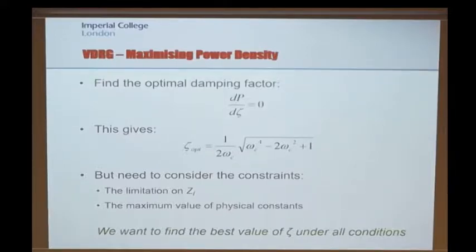Your spring won't be able to tolerate the amount of deflection that's required. Your mass will move outside of the swept volume. It'll strike the frame of the device. So there are practical limits on this that mean that we cannot set the damping factor all the way down to 0. What it's effectively saying is if we had an infinite volume through which to move the mass, then yes, the damping factor should tend to 0. But of course, as I've said, there's a limit on the total displacement we can achieve.